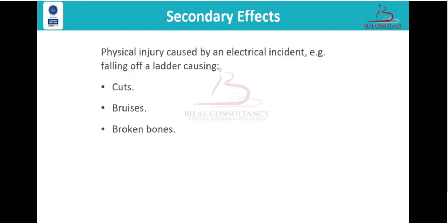Moving forward towards the conditions and practices that are likely to lead to accidents related to fire. Use of unsuitable equipment, for example, the use of non-intrinsically safe equipment in a flammable atmosphere. Use of equipment in wet, damp, or humid conditions. Misuse of equipment, for example, sticking wires directly into a socket rather than using a plug. Physical abuse of equipment, for example, pulling the plug out by tugging at the flex, carrying the tool by the flex, allowing the flex to be pinched, trapped, or crushed.